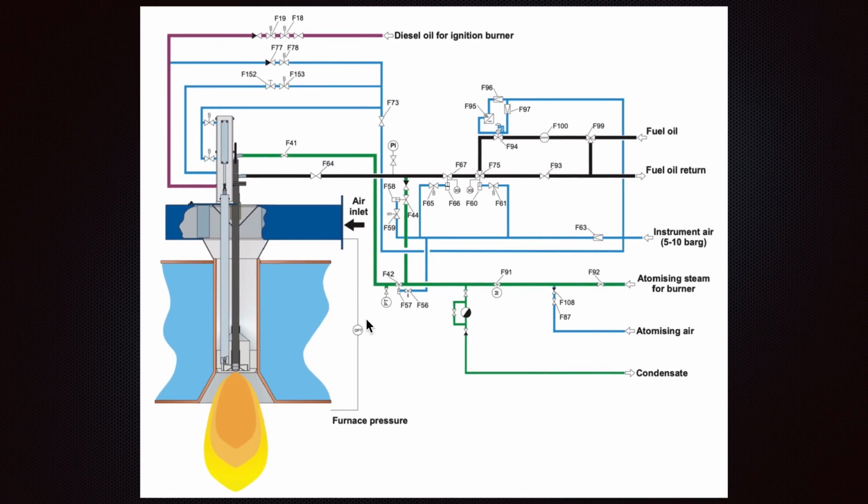You can see that we also have a differential pressure transmitter, which measures the air inlet pressure and the pressure in the furnace. Sometimes it's really necessary to disconnect the line here and here before the transmitter and blow pressure air inside, but not into the sensor, because you will damage the differential pressure transmitter.